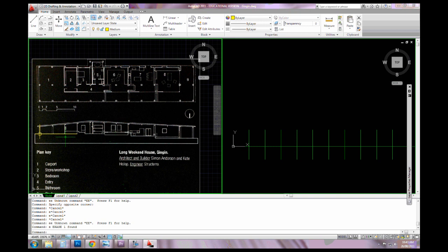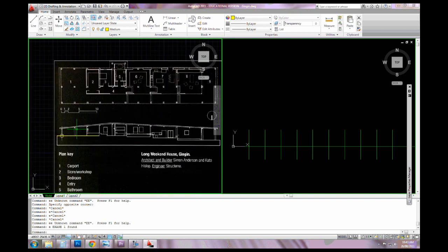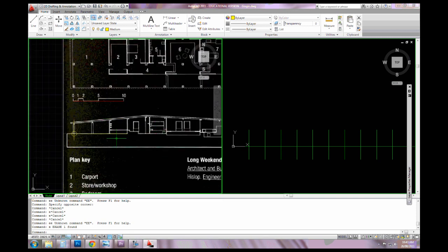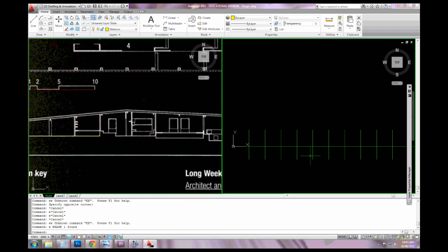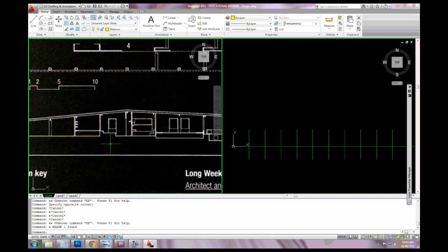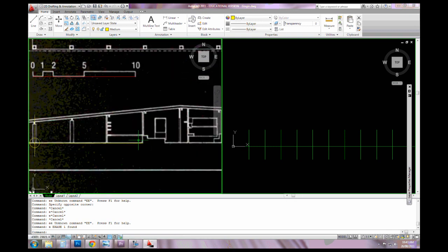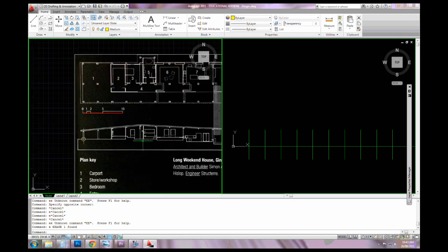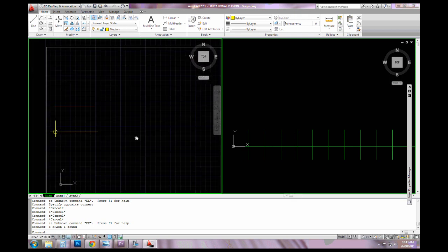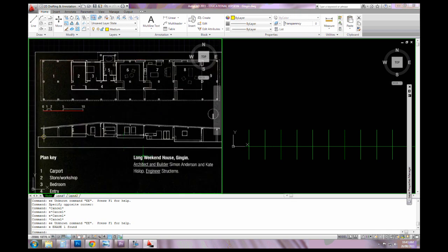The next thing we're going to do is use the distance command, and also the polyline command, to draw the ground plane, and then I'll draw the roof, and then some of the walls. We'll add to it slowly, just measuring elements off this image and then drawing them here manually, instead of doing the technique that you guys are used to, which is tracing. So you've got to adapt the right technique for the job at hand. This is more a representation of a physical document that you've got sitting in front of you that you need to manually draft up.